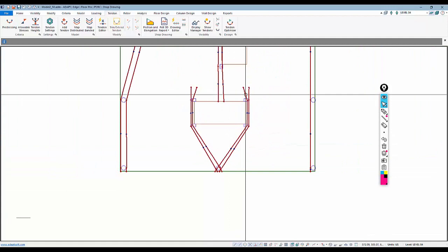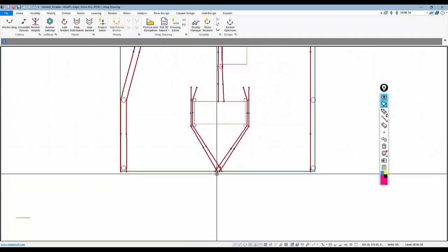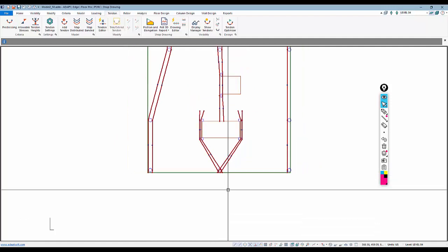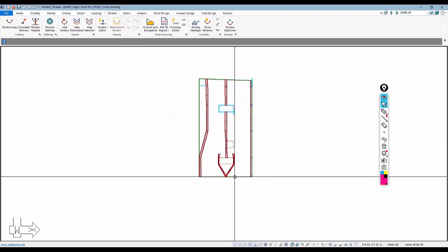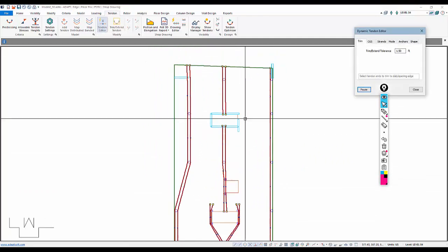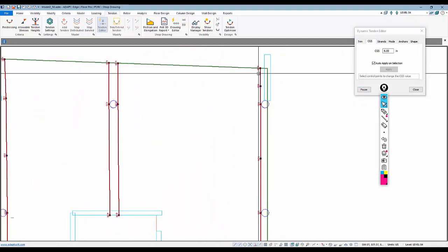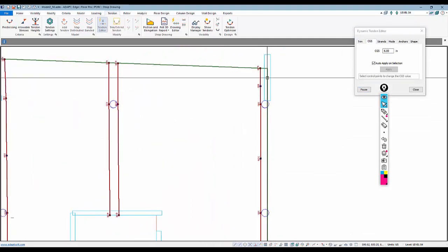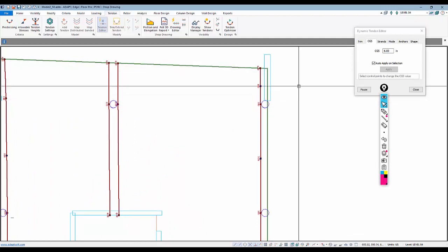Okay, so all of these tendons are just kind of ending at this support here. We're going to have fairly high precompression there because of that, and then they split to go to either side of this opening. If I come back into the tendon editor, I may need to make changes to the CGs elsewhere. So we can see this is a reverse parabola. There's a wall there, and we don't really need drape in that span, so I'm going to change that to 6.